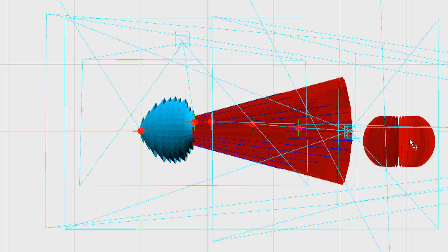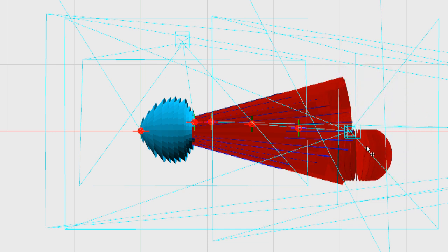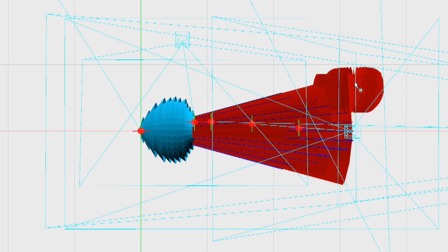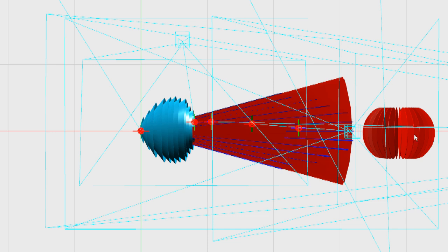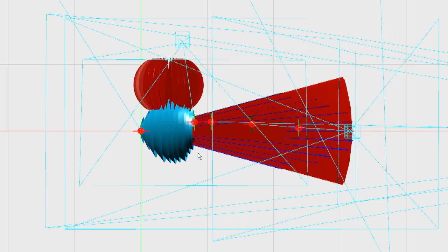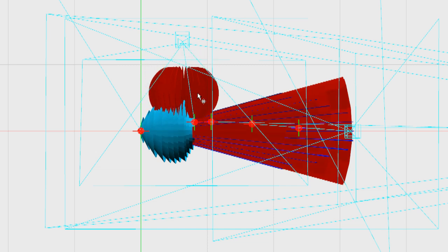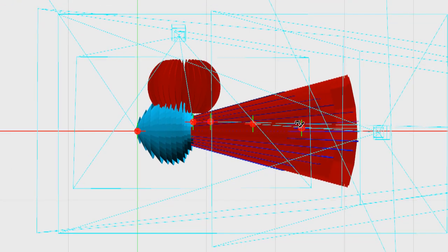I feel that would give you probably the best all-round performance, because you've got that long range on the antenna tracker with your Yagis. Wherever you are in the sky, the antenna's going to follow you. And when you come into land, even if you happen to be out of the field of view of the Yagis for a moment, the circular antenna is always going to be giving you maximum reception.